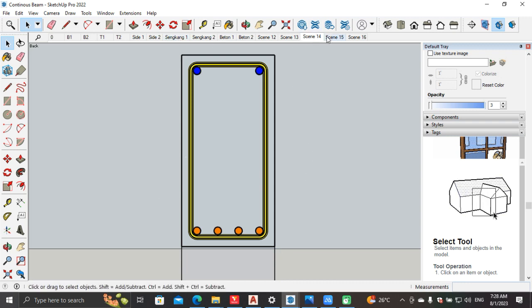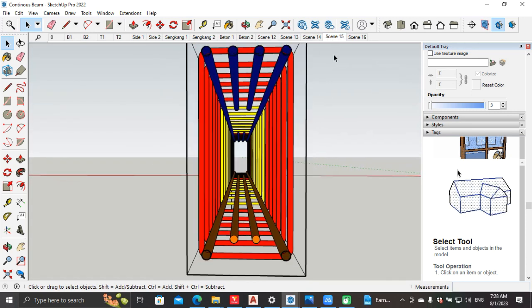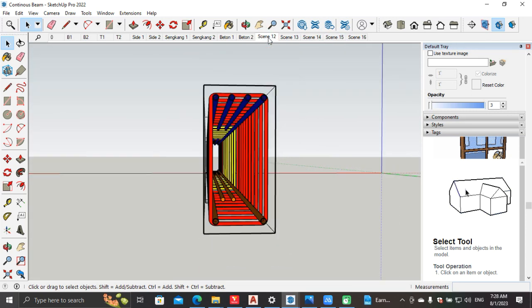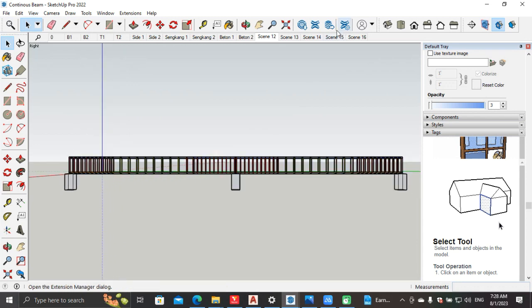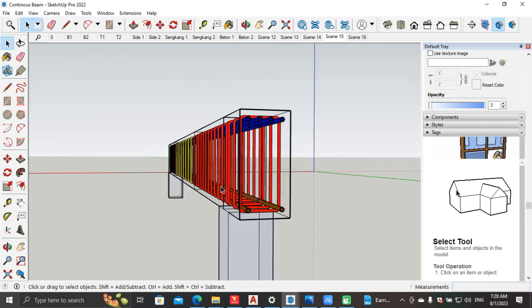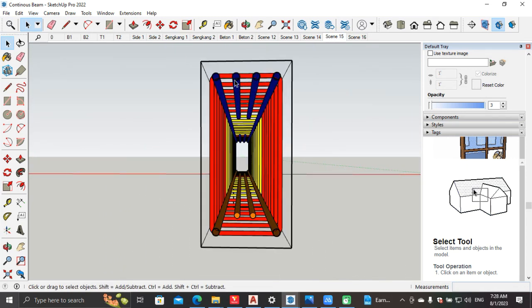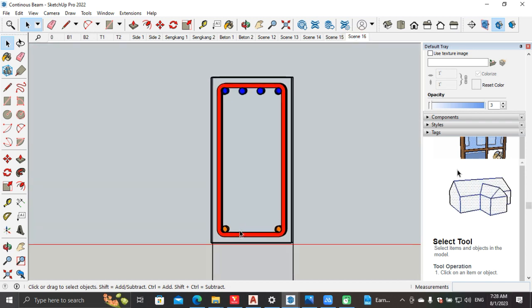This is the sectional view at the next one, and next we are cutting it towards the support. That is, here we are cutting. So you can see we require 4 number of bars near the support. Here we have cut all the 4, and this is given to continue the cage structure only. Only 2 numbers is given. So this is also cut, and this is not cut. It is curtailed in the middle itself. So the diagram will come out like this.